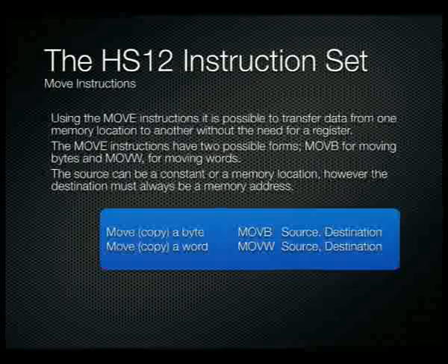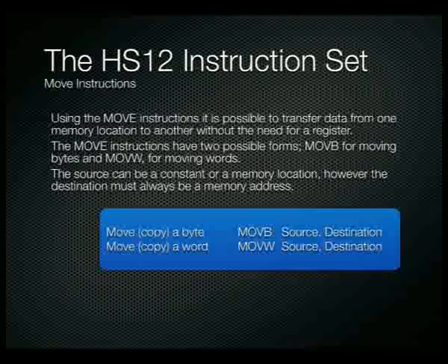So if you're doing something quite complex where you've got all your registers loaded up, you actually can just do a move without having to free up a register by doing a push, then loading the value into that register, storing it back, and then pulling the value back from the stack into that register. So it makes it a little bit easier if you're just simply using moves, because a move uses a temporary unnamed register inside the processor, simply loads it into that and then stores it back to some memory location. So it leaves our register set, so to speak, alone. So it's a really good way of moving data around.